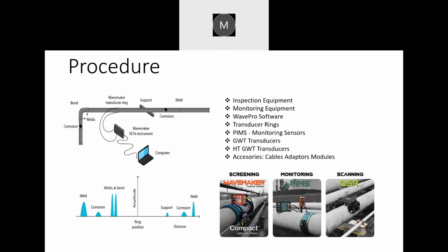For information on another inspection alternative, the sensor is read using 3D laser analysis for non-destructive testing and evaluation of pipeline corrosion. The results of the screening process are then inspected in more detail using conventional non-destructive testing methods. After that, a comparison of waves is illustrated in the figure above.